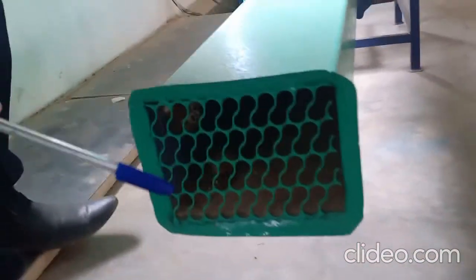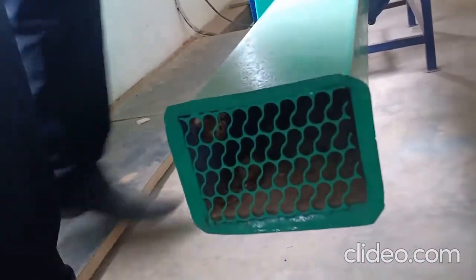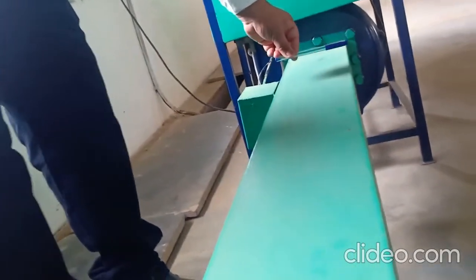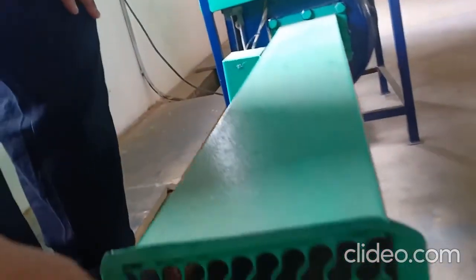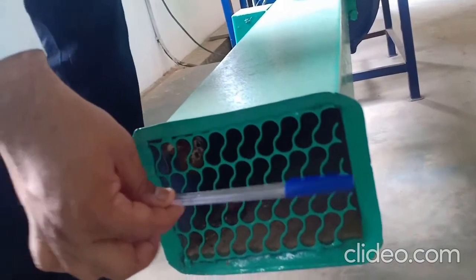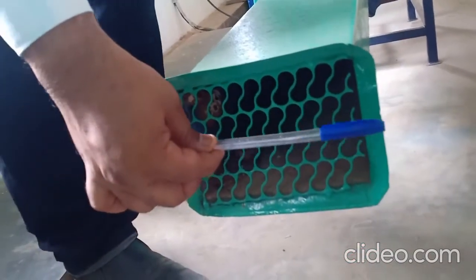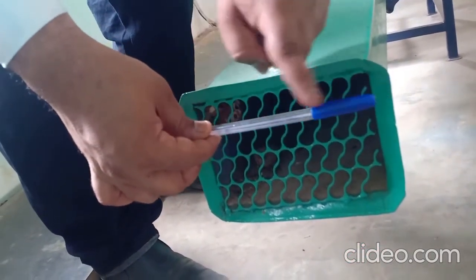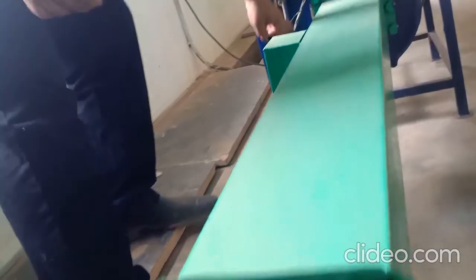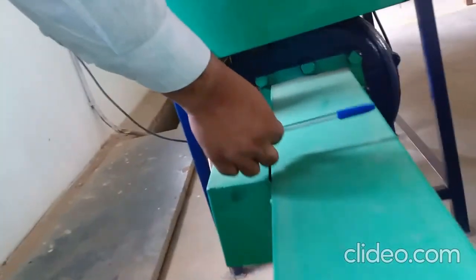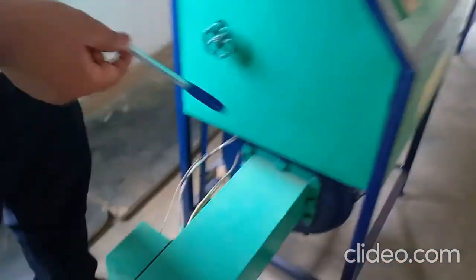You can see the pin, it is positioned in this way. The fin inside is positioned like this. At various points of this fin, the thermocouples are connected. See here, the fin is like this inside. So the thermocouples are connected at various points, and the temperature we can read out in this.